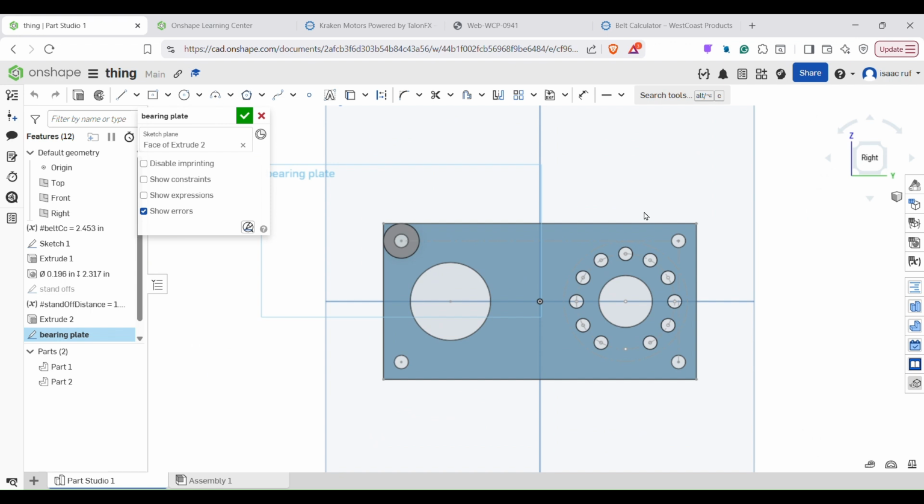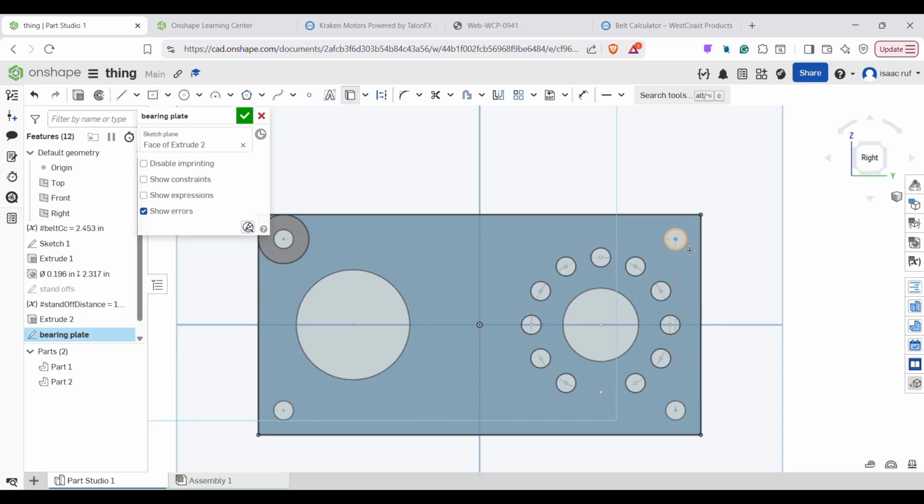So now that we do that, I'm just going to use this whole shape. So I'm going to click the whole thing and use it. And that gives us the outside. I also want these 4 little holes here. For this part, I think we're just going to through bolt it, just because. Actually, no, we'll tap these holes. So let's undo that. I'm not going to use these holes. I'm just going to use the point in the center of them. I'm going to use just the little point, and we can actually use that hole feature we had used before.